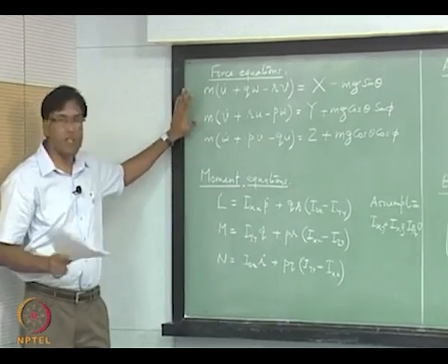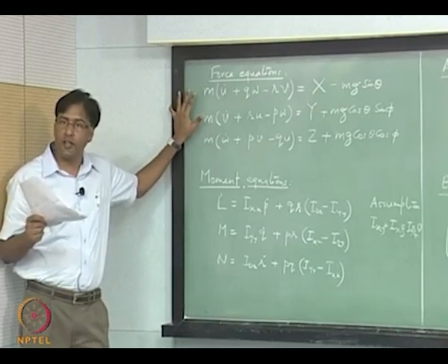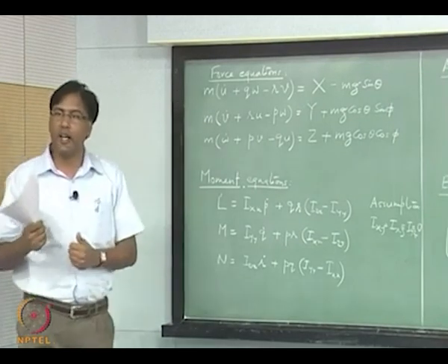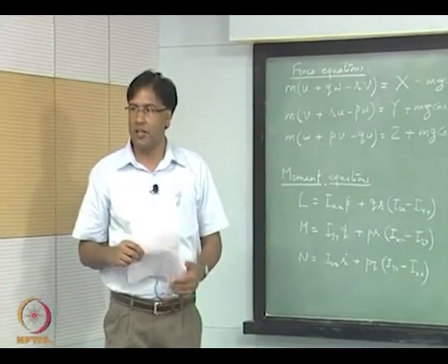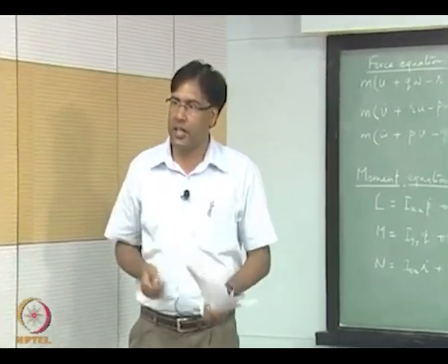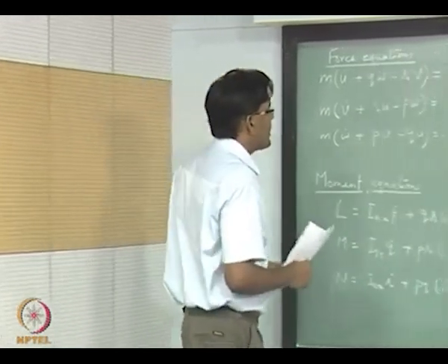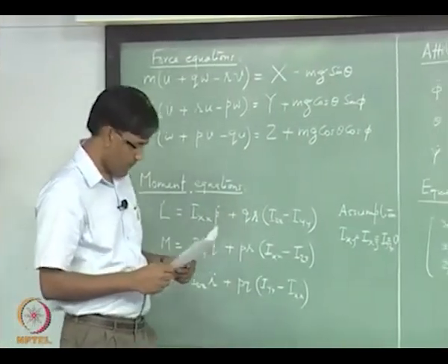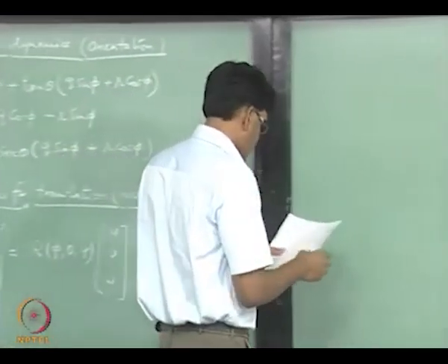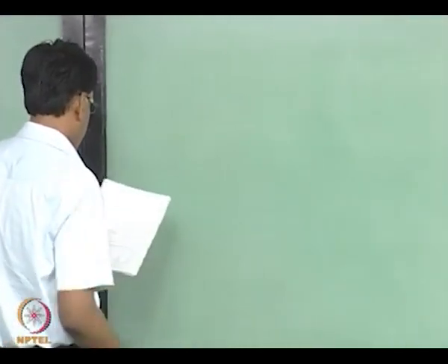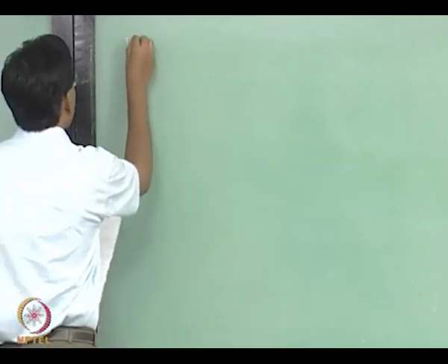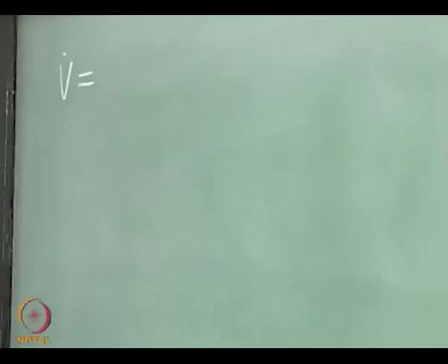So I will try to write these equations in the wind fixed axis system, because there we recognize the aerodynamic forces, right. We know that is drag, lift, and the side force. So I am directly writing down the equations, and I am assuming here that the thrust is acting along the x axis of the aircraft. Okay.